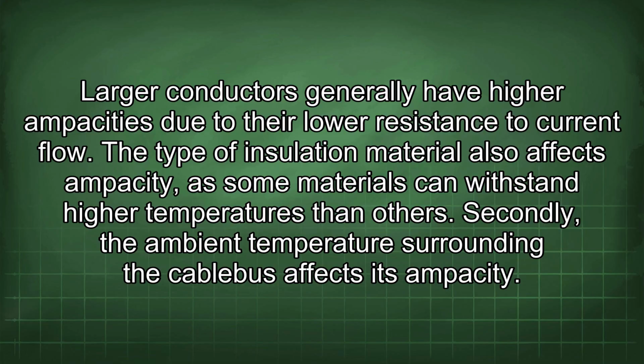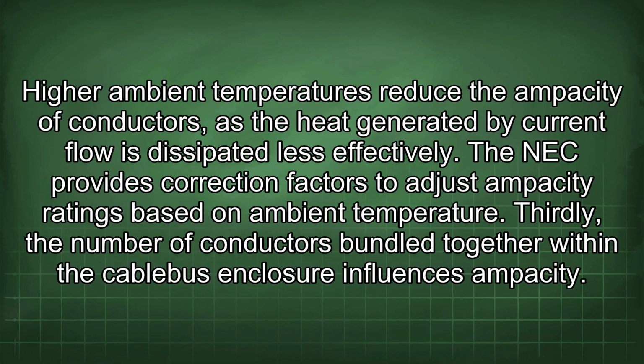Secondly, the ambient temperature surrounding the cablebus affects its ampacity. Higher ambient temperatures reduce the ampacity of conductors, as the heat generated by current flow is dissipated less effectively. The NEC provides correction factors to adjust ampacity ratings based on ambient temperature.